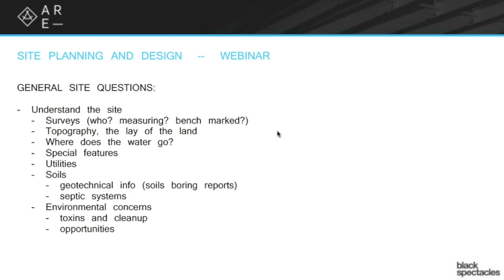The capacity of each of the different soil types, where the soil types start. Does the sandy soil stop at 5 feet below grade, and then it becomes a combination of gravel and sand? And then down maybe at 15 feet, it becomes bedrock or something like that. But each one of those will have a different capacity, different pounds per square foot capacity they can respond to. And that's something you definitely want to know about and be able to analyze.